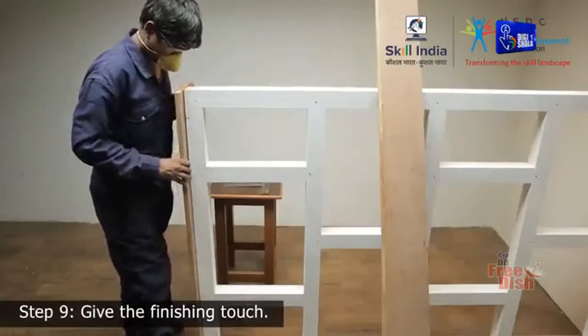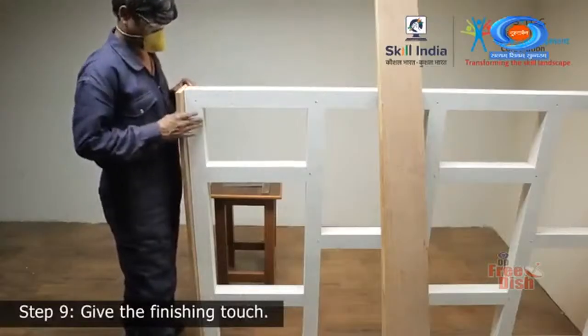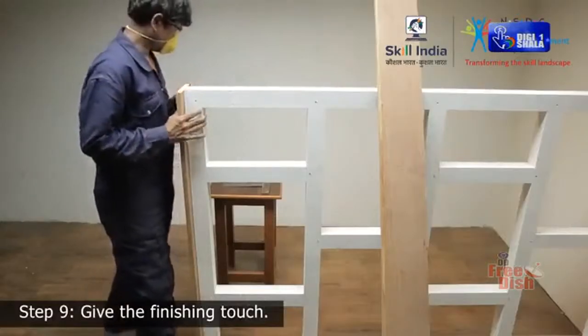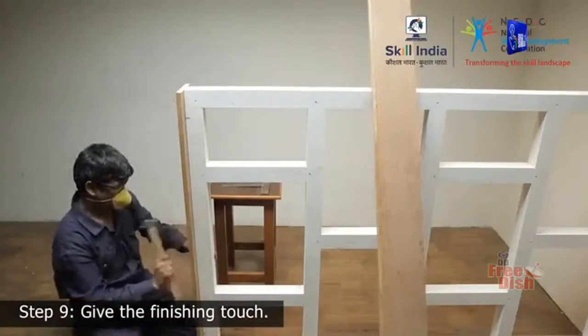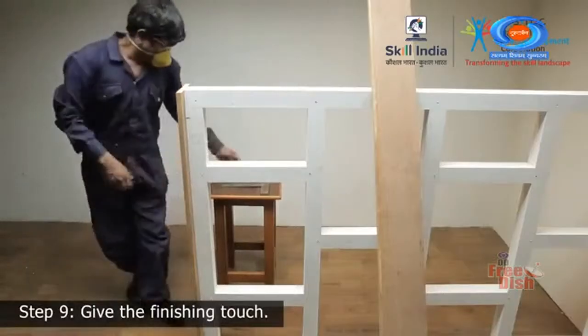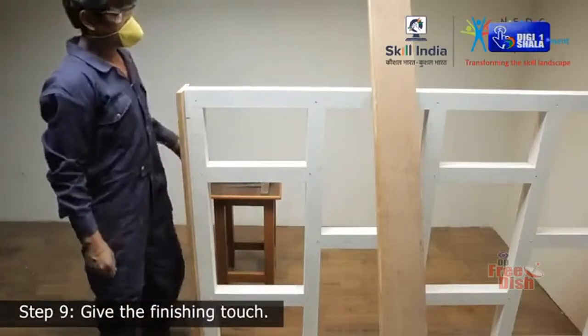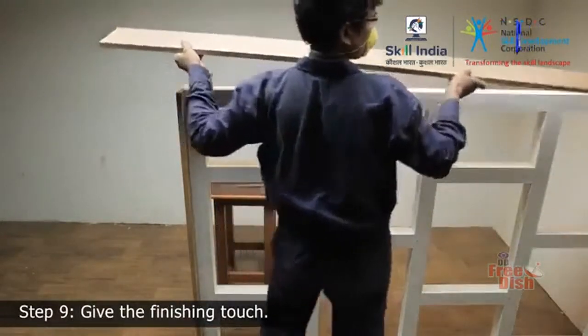Ensure that each sheet is of the same width so that they are perfectly aligned at the edge. Use nails to attach the plywood. Make sure the top edge of the plywood is flush with the top edge of the top member.